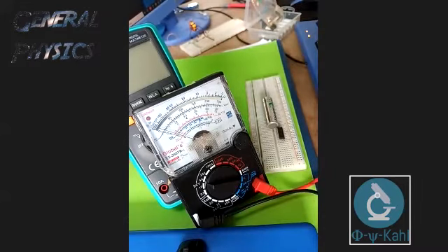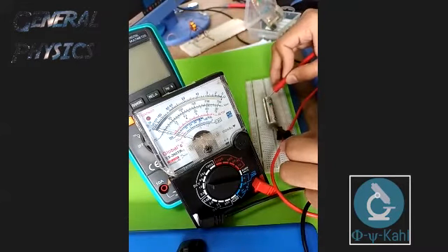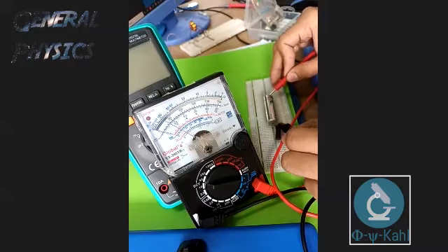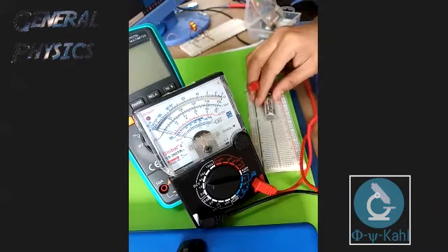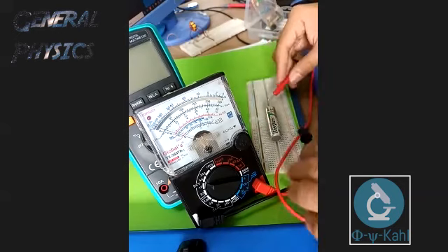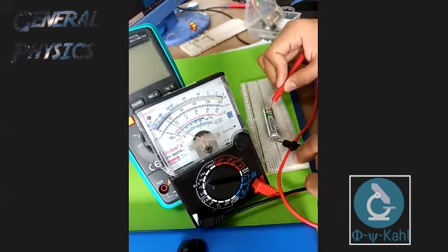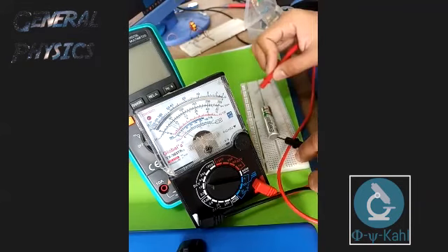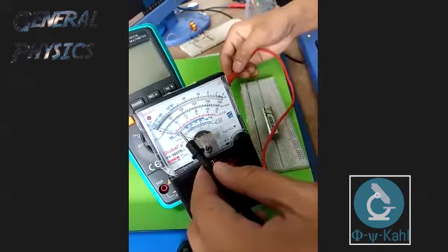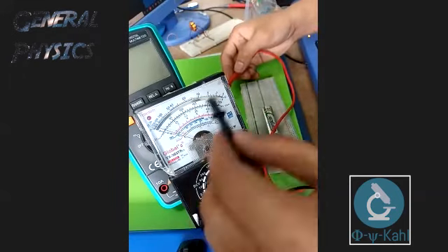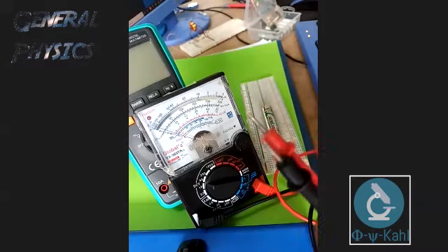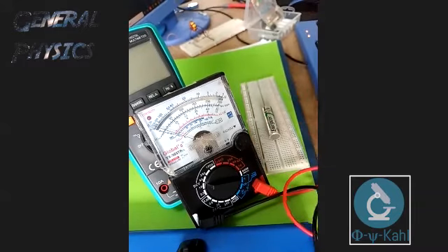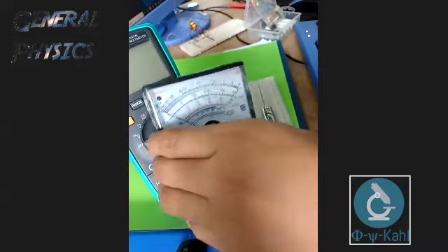So I'll put my positive terminal and negative terminal on the battery. Never mind this circuit, it's the IC. So I'll put it here, positive, negative, and the reading goes from 1 to 2, near 2. So that's 1.6. Three units: this is 1, then we have 0.2, 0.4, 0.6, so 1.6. That's our reading for the analog. Hope this is recorded so that modular learners will see the video.